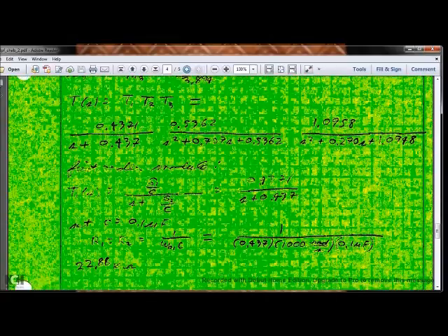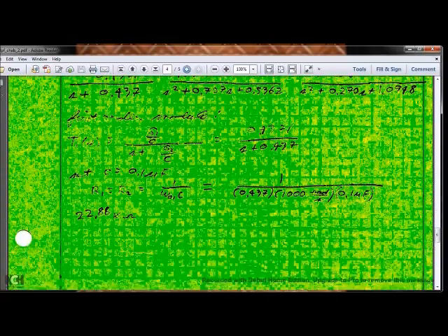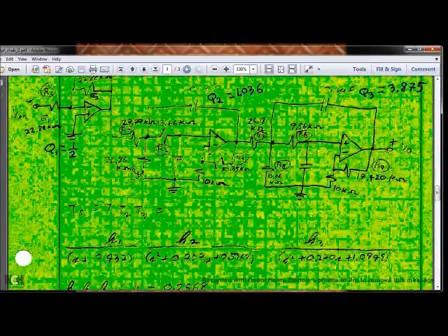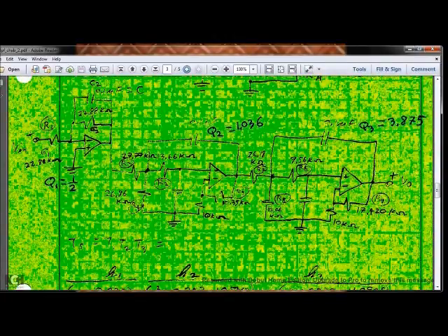You calculate these and put in for resistance and find that the filter actually works. Alright, we calculate the resistances for the first order section, 1 over omega 0 C, right up here. Here we have our R1 and R2 in the first order section.